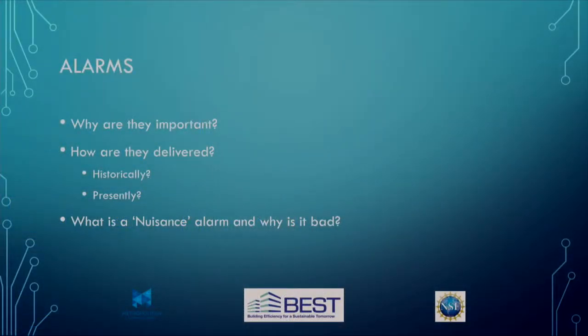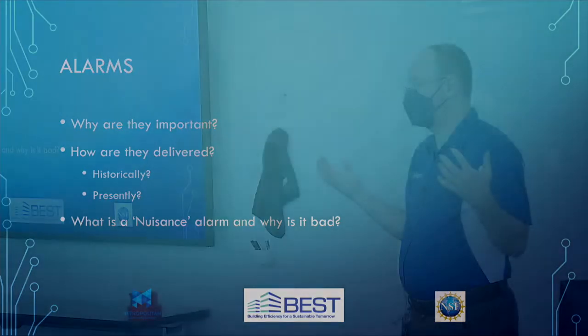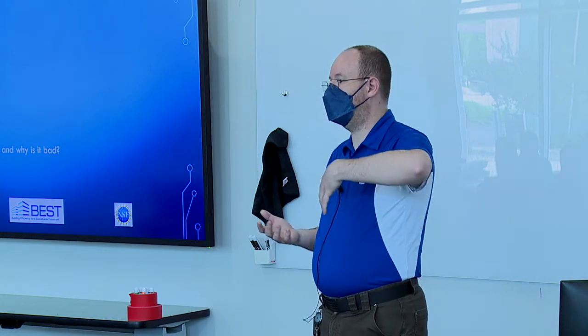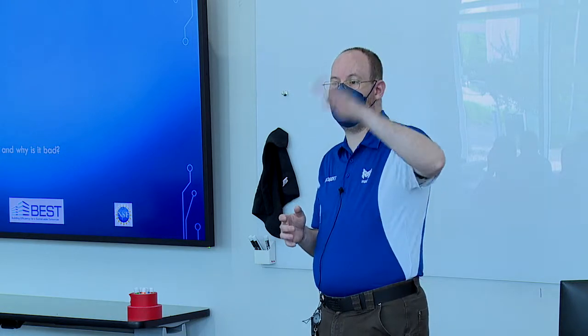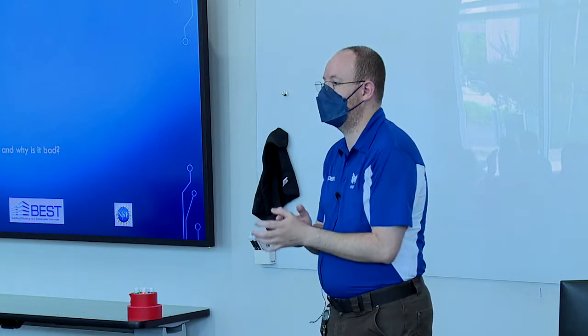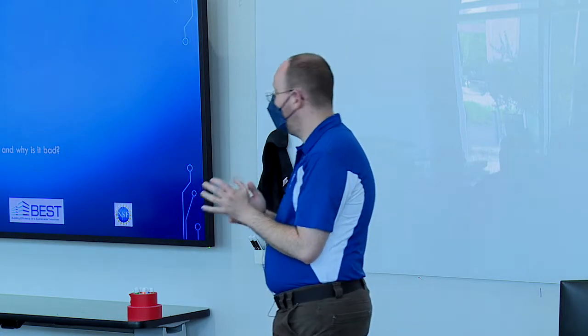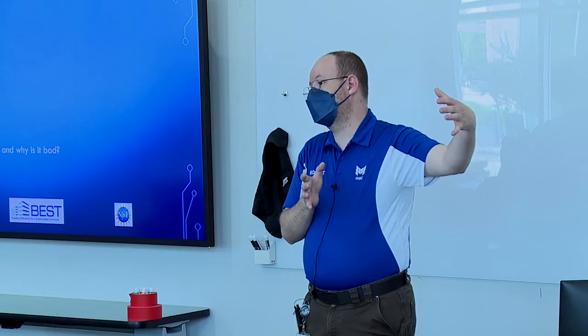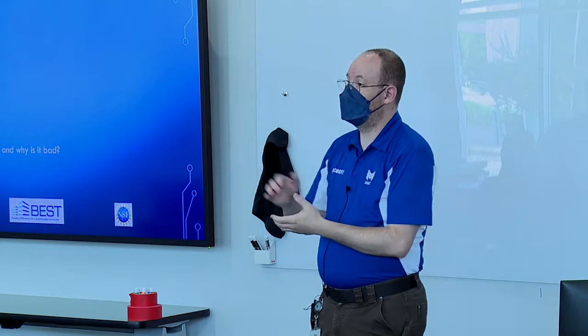Remember that comment about, hey, this went into alarm again? Nuisance alarms. When nuisance alarms happen, it's for a reason. Maybe things aren't set up properly for the alarm, or maybe we have a periodic problem that just shows up and, oh, it's an issue, oh, it's not an issue. Sometimes it's an alarm that was specified when the building was created that really isn't useful to the operators.